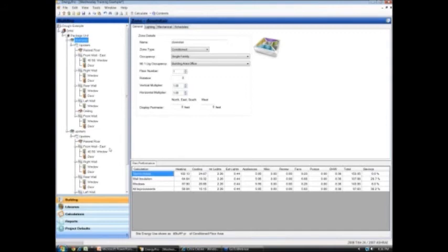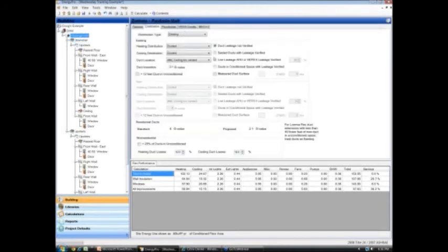Okay. Their question is, if you're testing duct leakage and you want to figure out the percentage of leakage, is it 21.7 CFM per ton BTUs of heating, correct? If it's a heating only system, it's 21.7 per 1,000 BTUs.